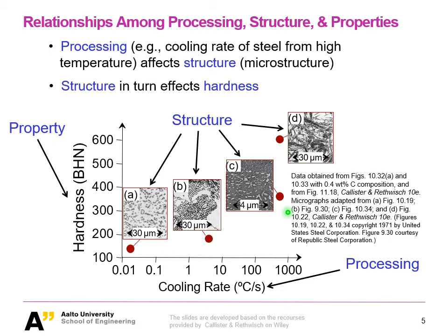Quenching is already there, because martensite itself is quenched. What you need to do is just a tempering. You will get so-called tempered martensite. This is exactly how it looks. You have ferrite plus very small, tiny cementite.